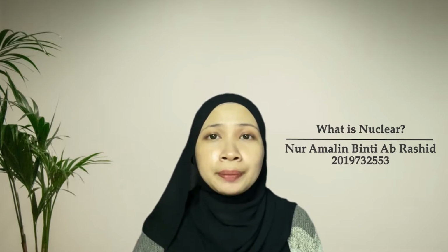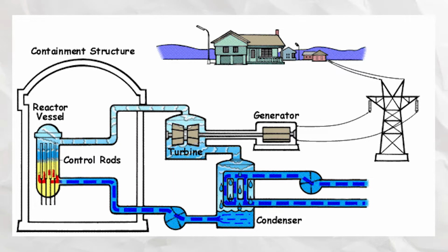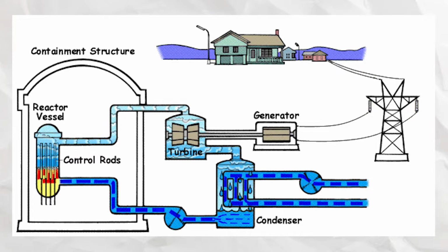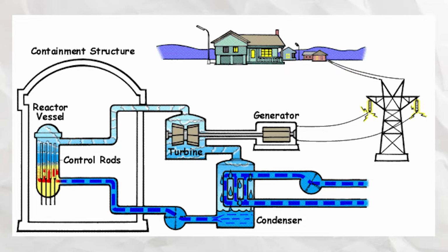BWR is also used for the generation of electrical power. In a BWR, the primary coolant water is maintained at lower pressure so that boiling and steam formation occur within the reactor core itself, which serves directly as the steam generator, while the secondary loop and heat exchanger are not present.